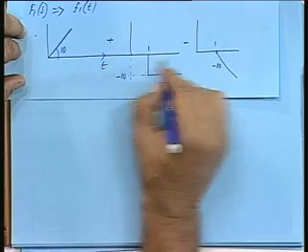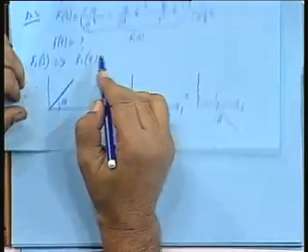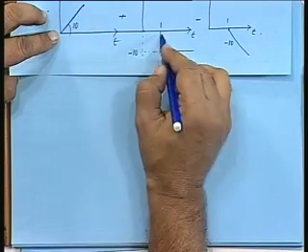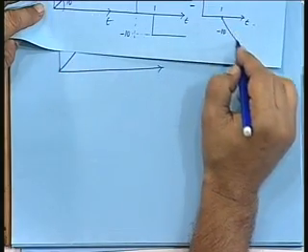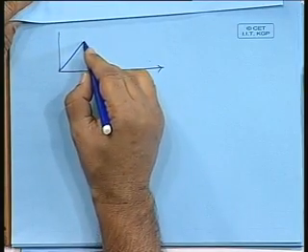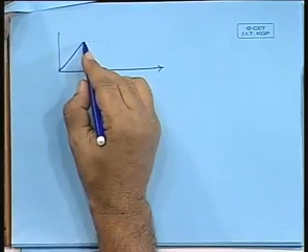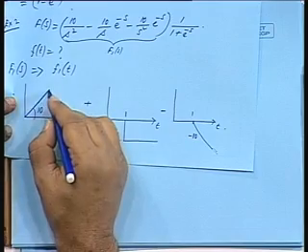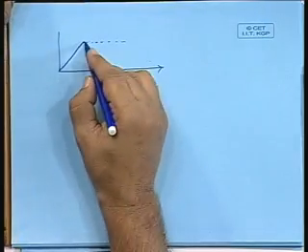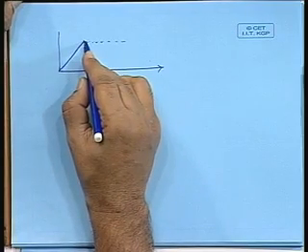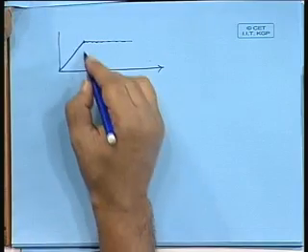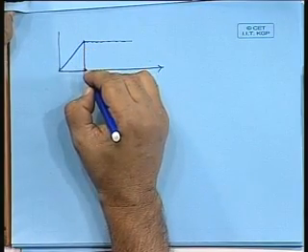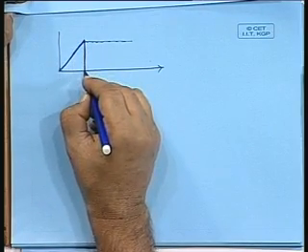These are all on the t axis, and these are the three components of f1(t) whose Laplace transform is this. So, f1(t) will be this one till it gets interrupted by the second part, which is a negative step, and again a negative ramp. A negative ramp will try to counter the increase. So, if I take this plus this, it would have been a function like this, but then there is a negative step of the same magnitude. See, after 1 second this goes up to 10 volts. Then it would have remained constant if I apply just a negative ramp of slope 10, but then there is a negative step also of minus 10. So, it will be coming down to 0, and this will be the net value of f1(t).